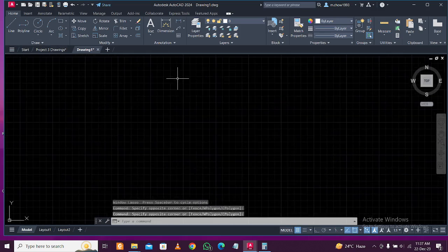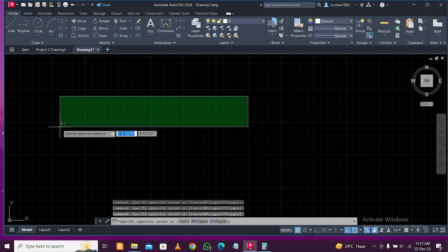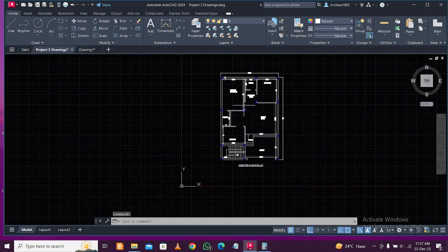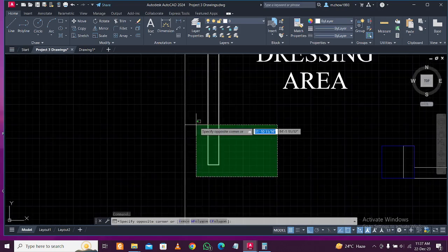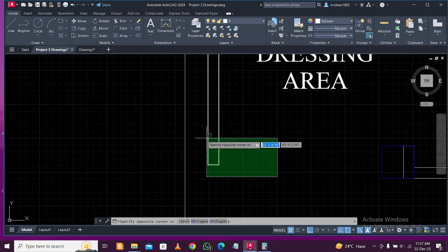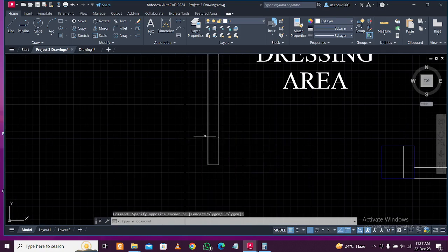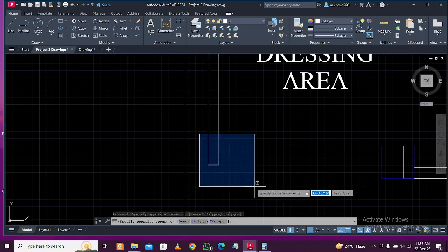So this is the blue and the green selection. I'll tell you about this later. Once you have the green selection on, that is the right-to-left selection, if you go across the screen, anything it touches gets selected.